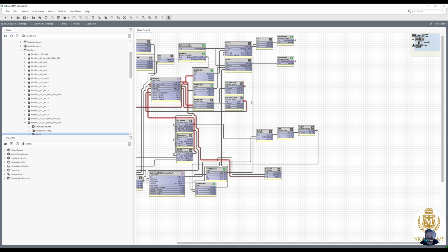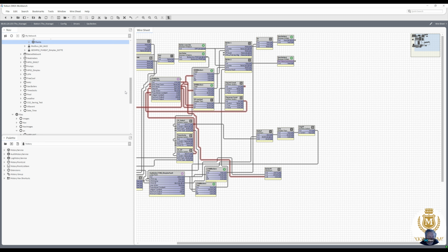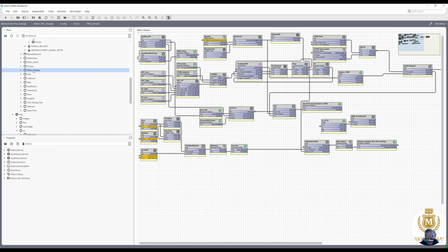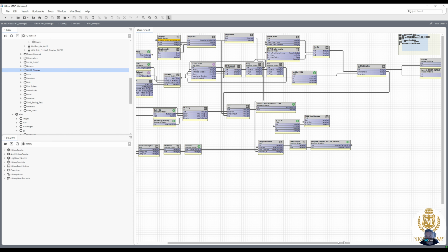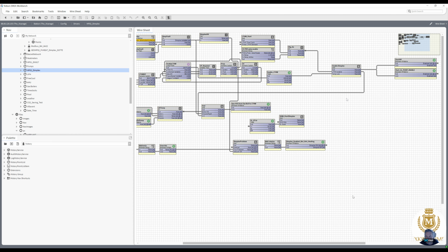Okay, let's go and have a look at the heat pump. The Dimplex heat pump. And then we can come back to that in a minute and have a quick look. Stale. So it looks like we're still giving an enable signal to the heat pump. Start heat pump and the ground loop pump. So why are you giving me an enable signal when we know you are off?